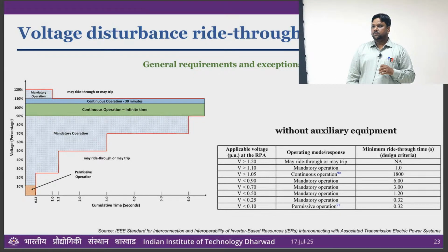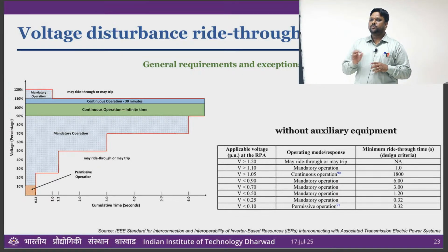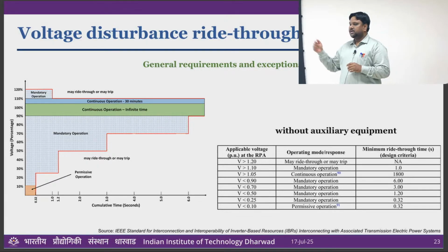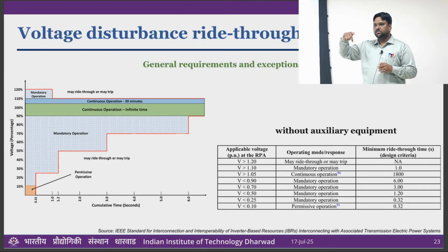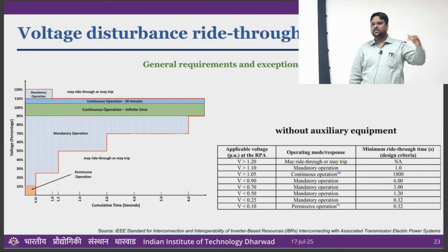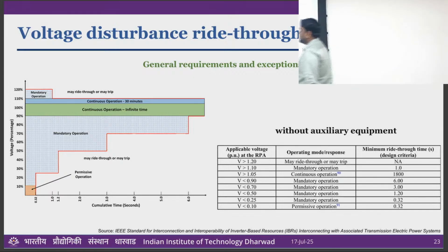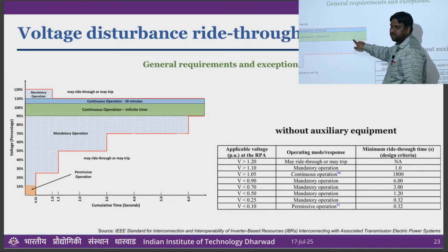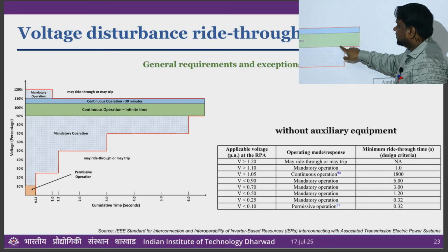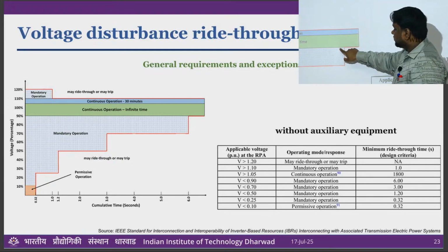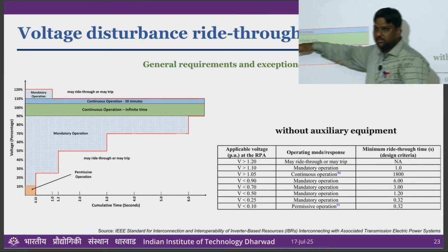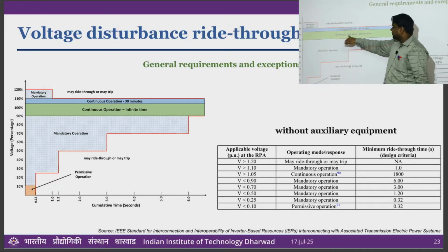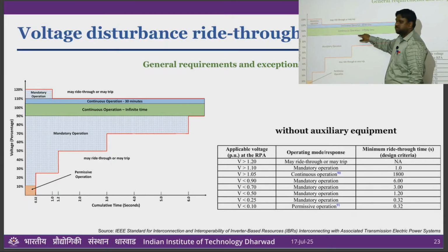grid complex. What happens? All these IBR power plants are tuned to respond to a fault based on POI measurement. But sometimes at POI your voltage requires fault ride through, but when you reach the terminal, you are still at a steady state point. Let's say I am exactly at this boundary point. POI voltage is, let's say, 89%, but still it is fault ride through, right? 90% is this line. This is 100% continuous upper steady state. Below that is your fault.